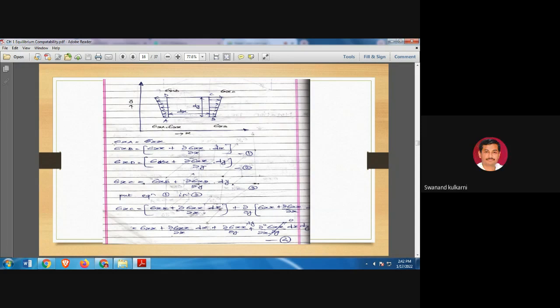So this is the stress at point B that we can understand here. So sigma xb is nothing but sigma xx plus dou sigma xx upon dou x into dx. This additional part represents differentiation of stress x with respect to x at a distance of x. That's why this additional part we have added in here sigma xb. Is it okay? Yes, sir. Okay, very good.